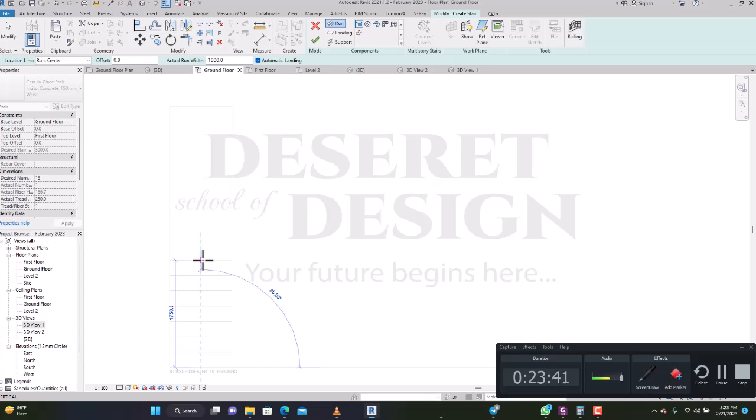These are the risers you are creating. By default it is saying we need 18. Do you get it? So it means I need to draw 18. Now you look down there, and you will see that it will give you information of what you have created and how many is left for you to create. Right now it's telling us that I have created 8 risers. I'm left with 10, because out of the 18 I have done 8. So you will see 1 2 3 4 5 6 7 8. So I'm left with 10 remaining. That information is being written here for you, that you've done 8, you are left with 10.